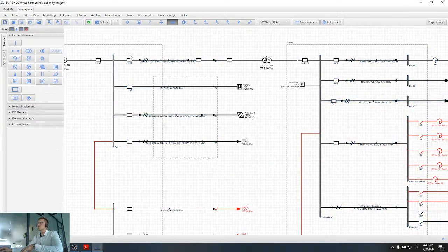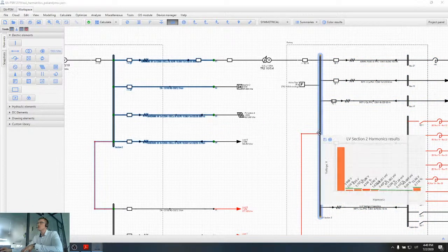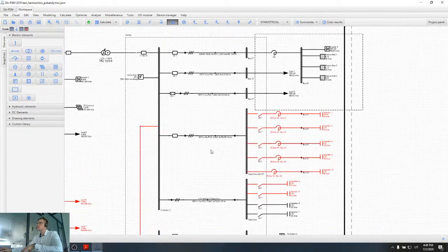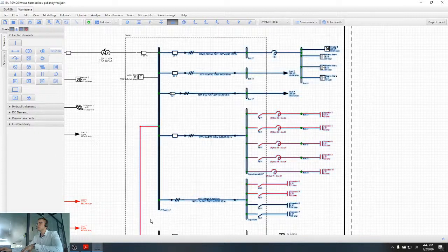It is not the best idea to try to solve problems on the medium voltage side. It is best to solve them on the low voltage side, where equipment is cheaper and it is easier to work. From the strategic point of view, it's possible to connect filters to medium voltage, but better not to do that if there is no necessity.